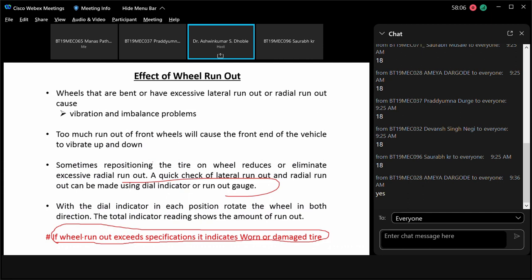Then I thought there is some kind of leakage, so we have to check that. To my surprise, I found that there was a metal pipe connection elbow fitted to the engine block, and that elbow had a hair crack, and because of that there was a leakage.